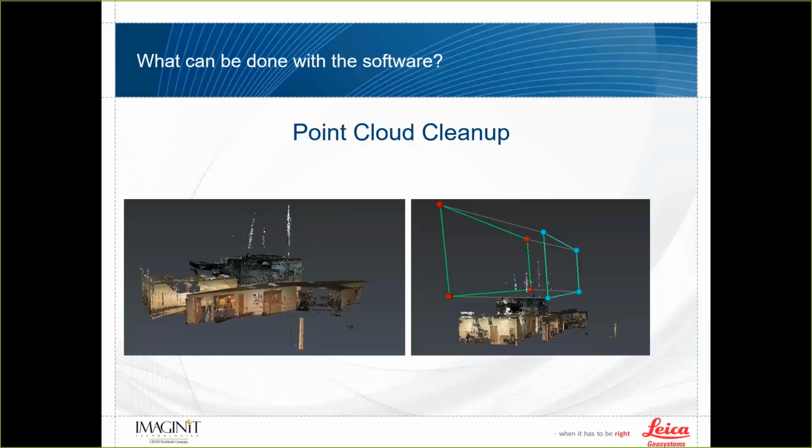So you can see I've got a full 3D box there. Now, for those of you out there that are using something like Register 360, you might do something like this with a limit box, and that tool works great. One of the reasons I like this one is because it's all in one. It's a selection tool limiting into a 3D space and allowing me to delete those points.